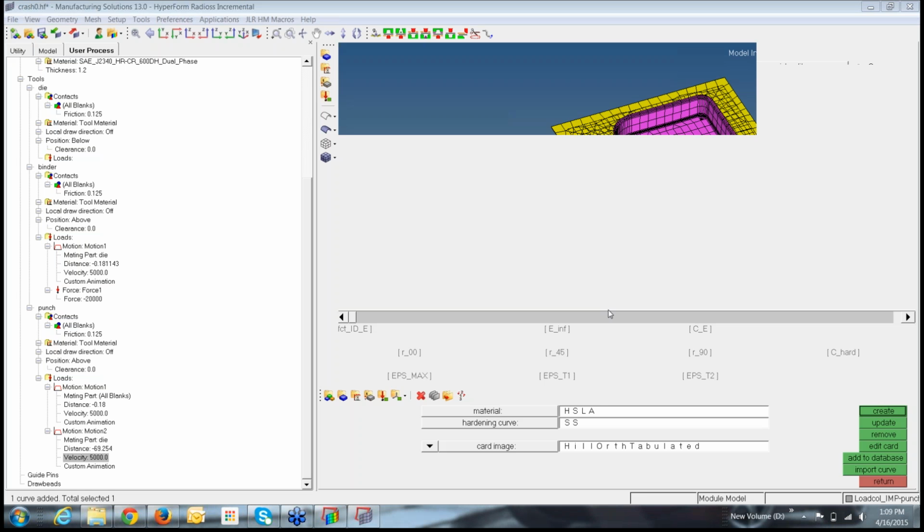So based upon the component, you need to spend time on which are your flanging regions, which are the trimming holes, when can you trim. The trimming hole initially will be oblong in shape, but when it gets formed, it should become circular in shape for your circular holes. So you need to be very careful about how you form the component, when you do the trimming stages, when you do the flanging stages. It comes with some experience and your judgment about the component.